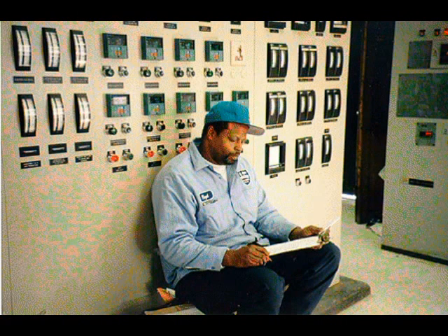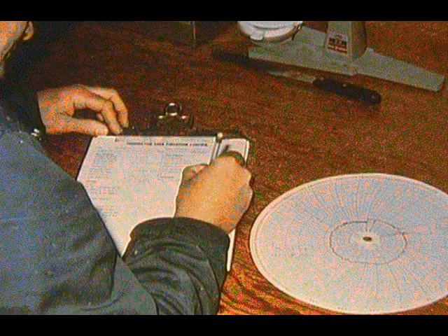This means that the standard duties will be noting changes in running sounds and vibration of pumps, noting bearing temperatures, performing pump startup priming when necessary, checking suction and discharge gauges, observing flow rates, tracking motor readings, including amperes and hours, and maintaining other records of pump operation and fluid sampling as required.